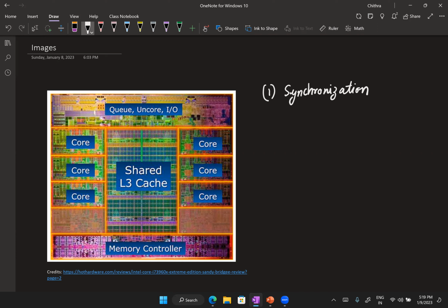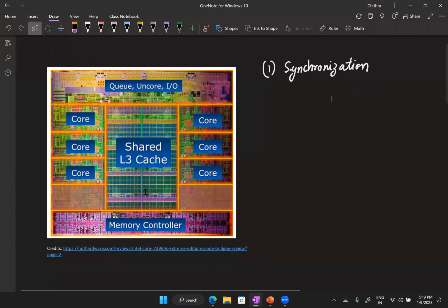Now, of course, it is not necessary that this entire block is going to be running at a single clock. You could have a clock and its divided down frequencies, or you could have multiple clocks and the associated divided down frequencies. So when I say divided down, for example, let's say I have 100 megahertz, its divide by 2 is very easy to generate. So if you have 100 megahertz, it's very easy to generate a 50 megahertz, 25 megahertz, etc. from it.